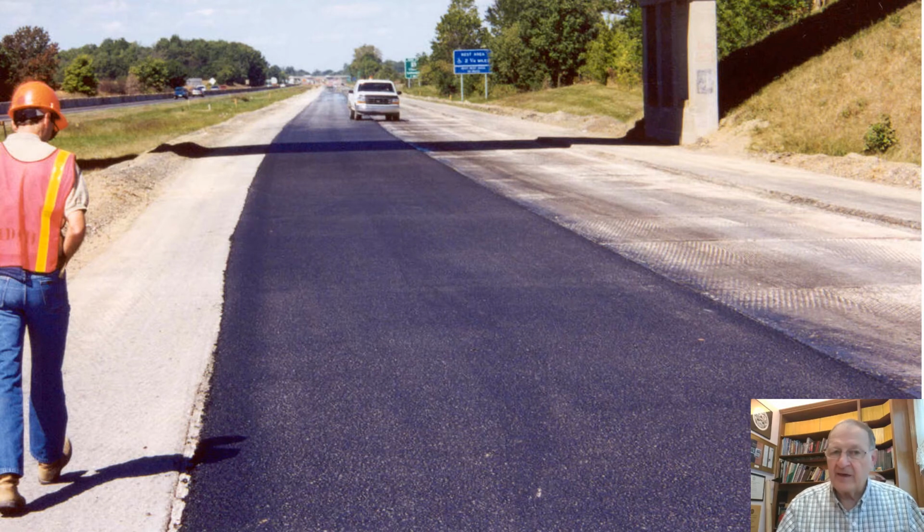Now, you might think, based upon that, that perhaps the rollers were moving too fast. They indeed were not. The typical rolling speed is about 3 miles an hour, which is just a nice, comfortable walk speed. And the rollers were running about 3 miles an hour. But we said, well, hang on. Let's reduce the rolling. Let's cut it in half. Let's roll it about 1.5 miles an hour.